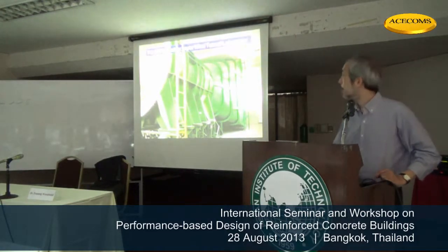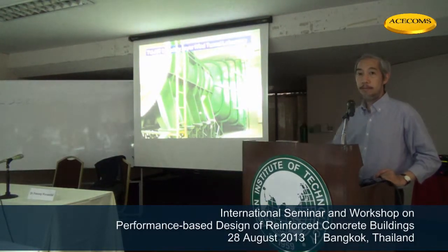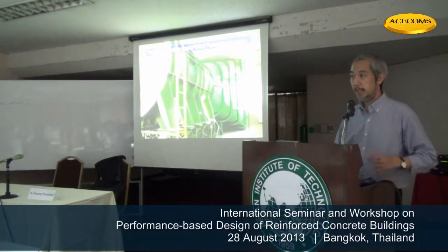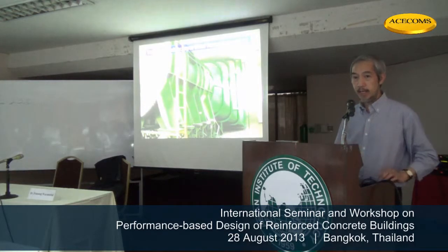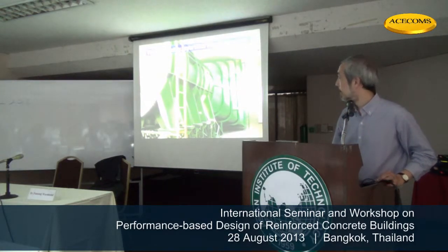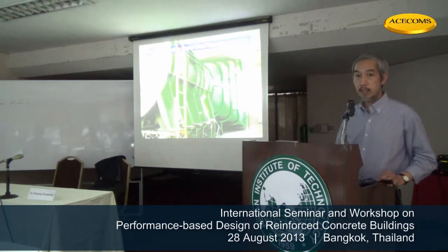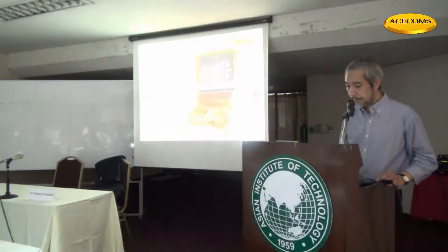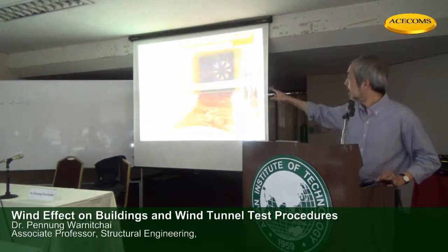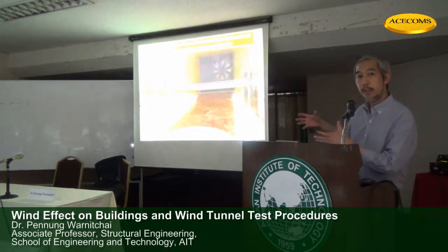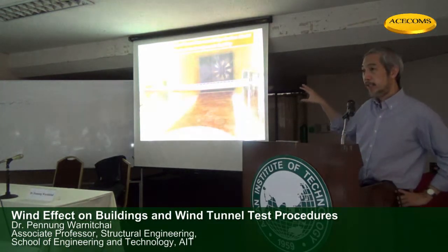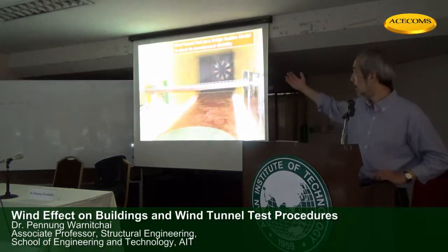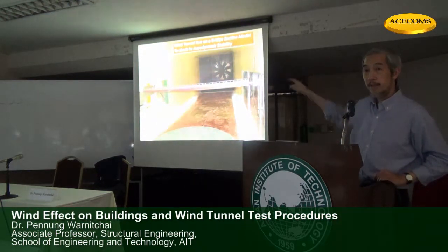This is an example of a wind tunnel. It's a wind tunnel that we made. It's developed by AIT and Thammasat University, our neighbor. We invested in making this facility. It is now the largest wind tunnel here in Thailand. Inside the tunnel, a section of bridge is put here, okay, and hung by springs outside. So the bridge section is exposed directly to the wind coming from the fan. You can see on the back.